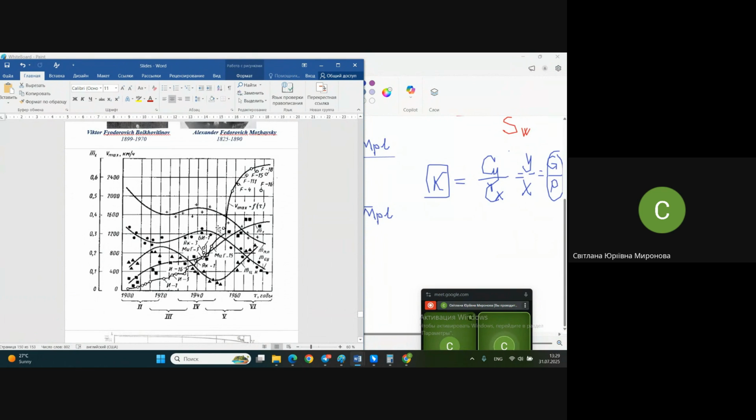And the very first stage, in nowadays conditions, when we already have statistical data about relative weights for one or another class of airplane, the very first step of any such design is to collect statistical data on the prototypes, let's say, the airplanes which have similar flight performances, similar payload, similar purpose above all, of course, and analyze their relative weights.